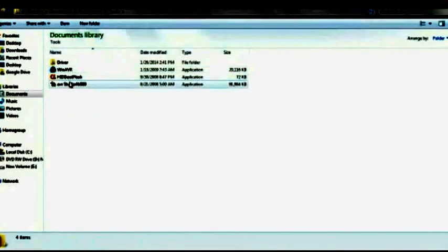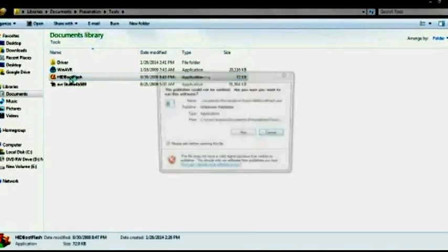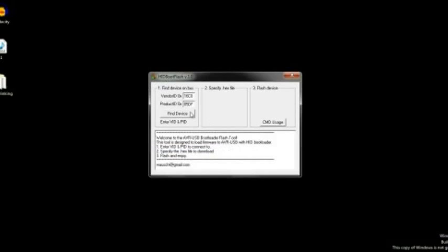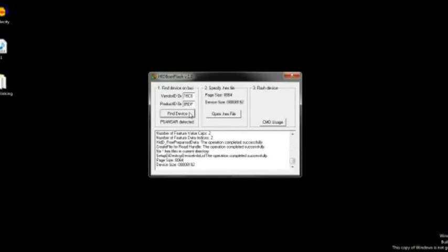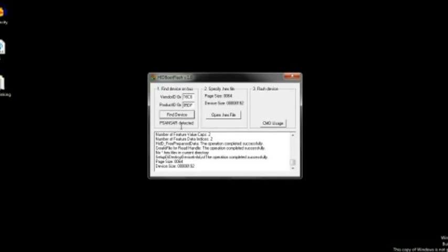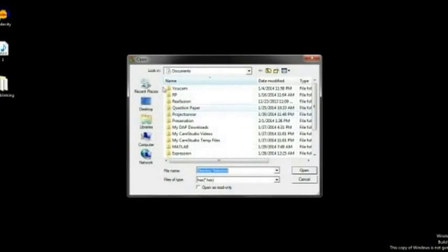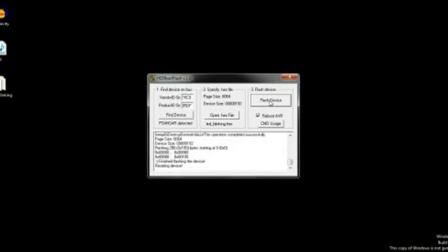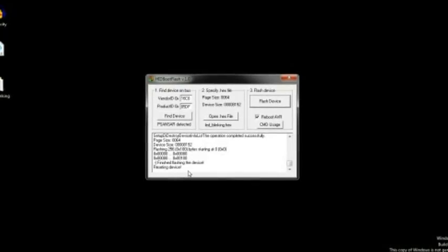So, next I go to the tools and I take out the software which would be used to burn the software into the microcontroller. Run. Yes. So I go to the find device. After connecting my board, it senses the ProjectSansar detected board. I select the hex file which I wish to put in the microcontroller, and I click on the reboot AVR, and when I click the flash device, it would reset the device and you would see the 4 LEDs blinking in your microcontroller board.